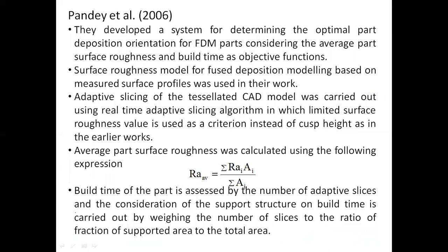Then in 2006, Dr. Pandey developed a system for determining orientation of FDM parts. He considered the average part surface roughness and build time as the primary objective functions. This work was focused mainly on FDM parts, and later it was found that this algorithm works very well for SL as well as for SLS also. SLS is selective laser sintering. I'll explain that when I do the process. So it also worked very well for SL as well as SLS processes.